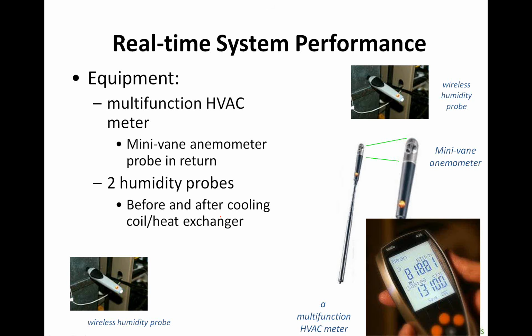So these types of things, especially when we're commissioning new equipment, let you document that when you install the new equipment, it was operating at its full capacity. Go back in a year later and check that equipment again and show the consumer that it was operating at 81,000, but now that the filter's dirty and the blower's a little dirty, it's operating below its rated output, right? So now we need to go ahead and clean it and then test again. It's a very quick, easy way. It takes less than a couple minutes to actually have that reading in your hand.